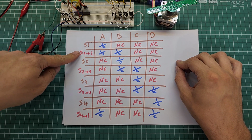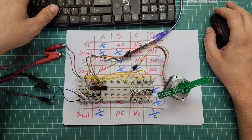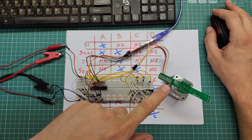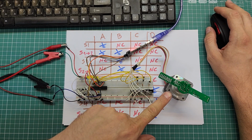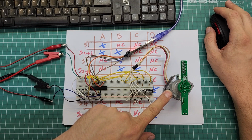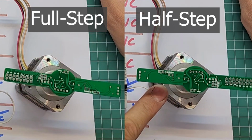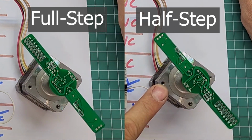To do this, we just need to alter the code. The driving circuit is okay. Let's try this. This is running at full step, and now it is running on half state. You can see the difference. This method is called half step or half wave driving, and now the steps are a bit softer than before, but the steps are still rough and not completely smooth.